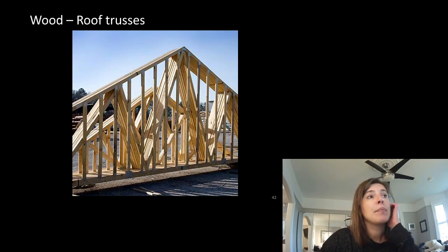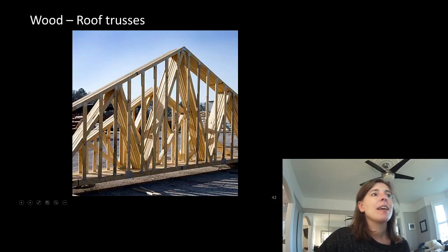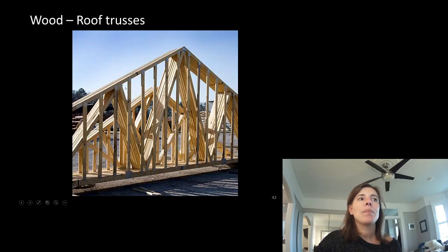Here are some roof trusses getting ready to be installed. They must have 2 different roof heights. Look at this one at the end. The reason the roof trusses work so great is we follow the best line of support. But at the end, we need our plywood to go on a surface that is only going to span 16 inches. So we need these elements for our end walls to be every 16 inches. And then most likely this doesn't need to be an engineered truss in the same way, because below it you will have studs at 16 inches on center.